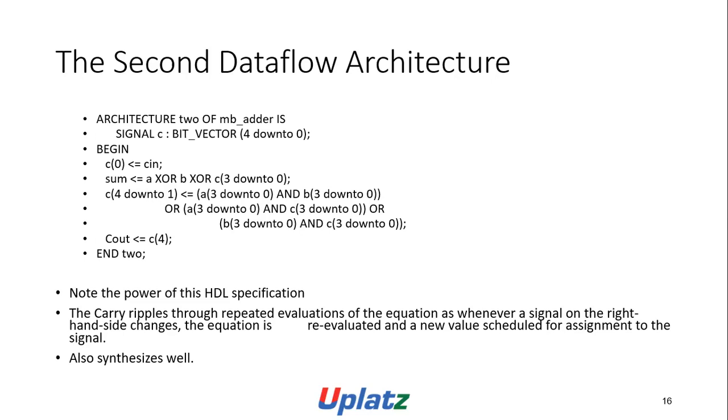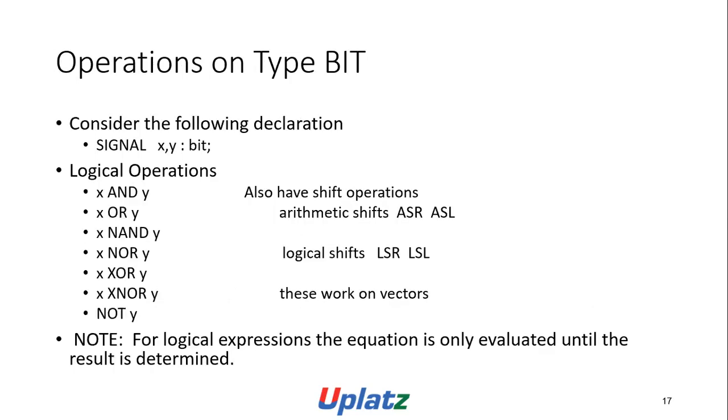Now the power of this HDL expression: the carry ripples through repeated evaluations of the equation. Whenever a signal on the right hand side changes, the equation is re-evaluated and the new value scheduled for assignment to the signal. It also synthesizes well.